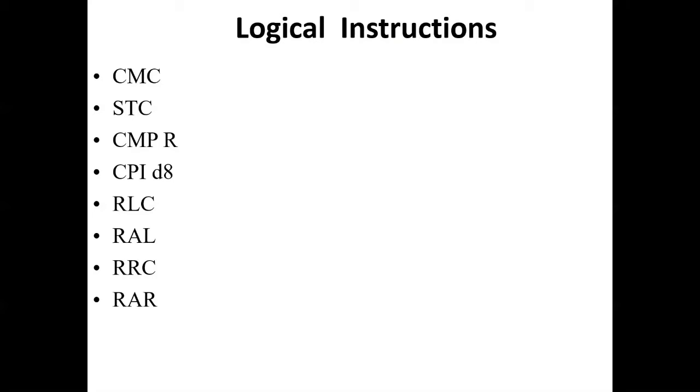Next is STC. STC stands for set the carry flag. It sets the carry flag to the 1 state immaterial of its earlier value. So if the carry flag is 1, then also it will set to 1, and if it is 0, then also it will set to 1. So ultimately the carry flag will be set to 1 after the execution of this instruction.